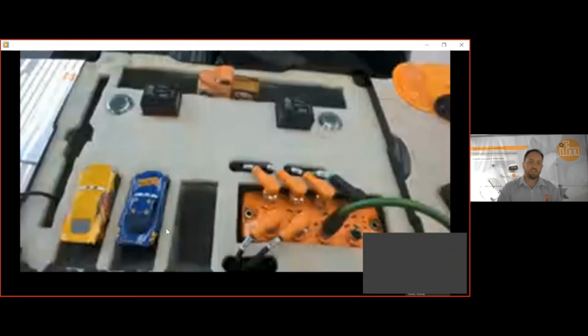Okay, so this is a nice little demonstration kit that IFM developed for us, and it uses, as you can see, kids' movie cars to hype up the application, or just make it interesting, I suppose. We have an Ilink master, and each one of those cars has an RFID tag. The black squares you can see are the DTR 513 Ilink RFID readers, and the little buttons are the capacitive push buttons, KT series, that we also have on Ilink from IFM.